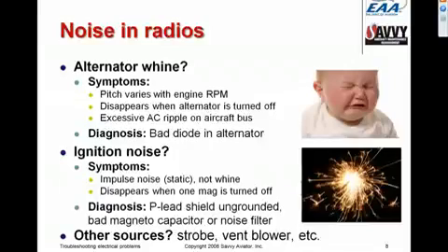If you've ever been listening in your car to an AM radio station, a weak AM radio station, and a big giant truck pulled up next to you, and you heard a bunch of noise in your radio, that's what ignition noise sounds like. Again, the way we diagnose that, first of all, is to note that it has that staticky quality, and second, that it disappears when one or the other mag is turned off.